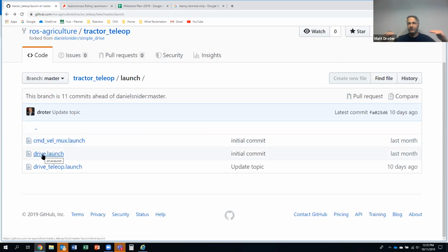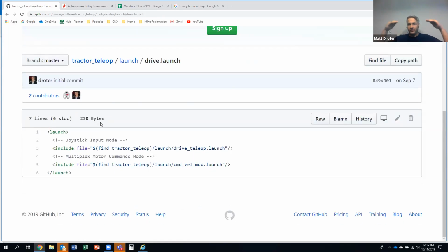So this is how the system is configured, if you look at the introspection: this one launch file launches two nodes. Got it. So it's kind of like step by step, built onto each other. Now what we would do normally is take this drive launch that's launching both of those launch files, which are launching other nodes, and put it into your base station bring up launch.